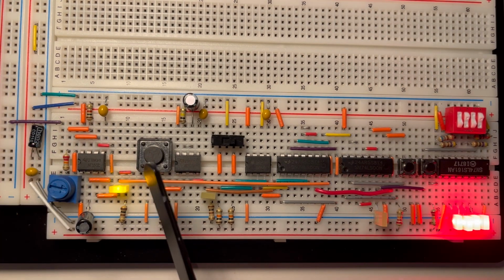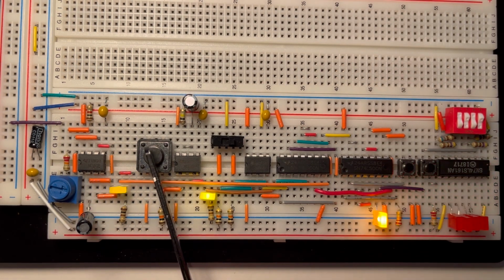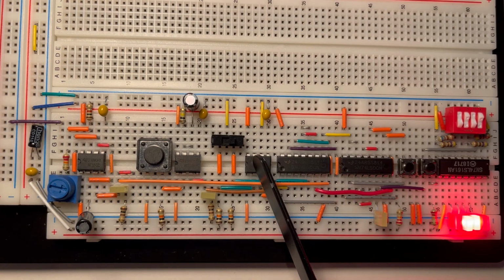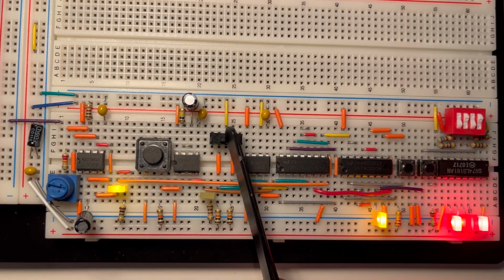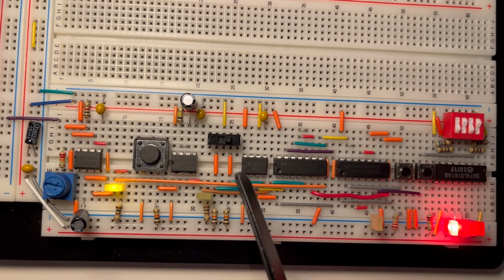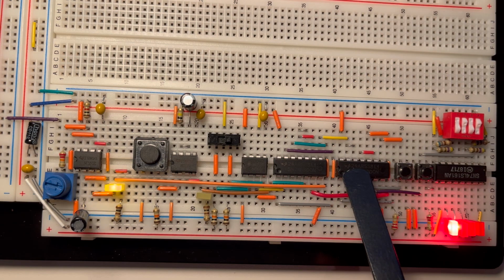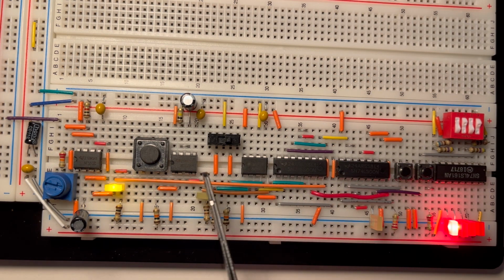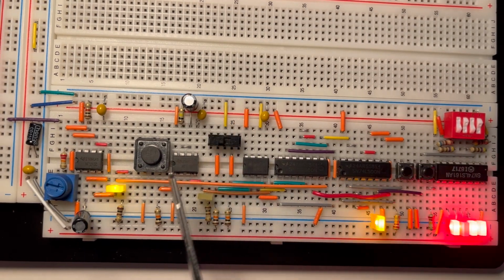The next is in monostable mode, which gives us a rising edge whenever this button is pressed. It essentially acts as a debouncing circuit. Finally, this 555 is in bistable mode, which gives us either a high or a low, depending on the position of this slide switch. The outputs of the 3 555s are then fed through these 2 NAND chips using combinational logic, which allows us to select between either a manual or an automatic pulse that advances the program counter.